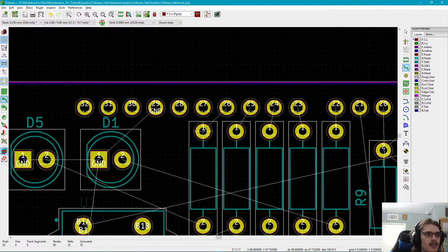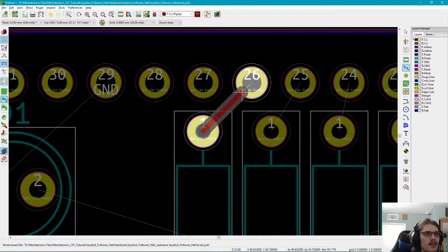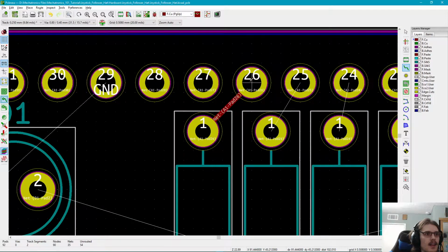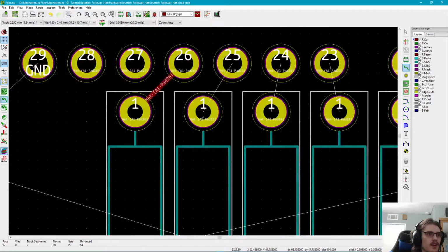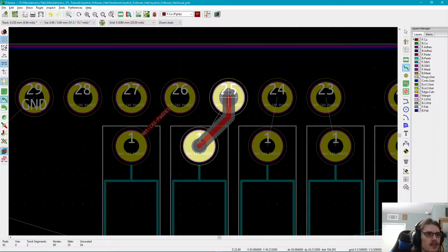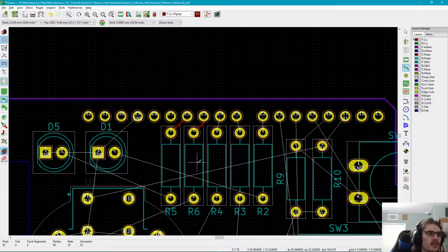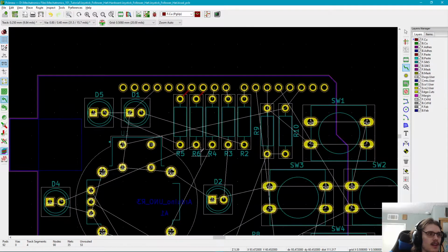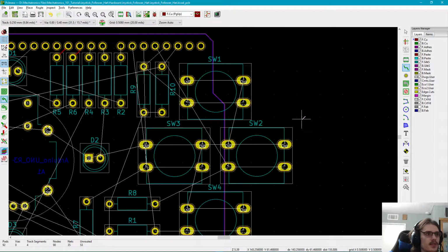I'm going to start at the top right here and see if we have enough clearance to make a connection directly to this. So I'm going to left click on pad 1, and yeah, that's as clean a connection as you can get. That's really close and nice. Most of the time, it's not going to matter too much how far it is, but keep in mind sometimes if you're dealing with analog signals that need to be analyzed, the further the trace is, the more it loses some of its strength.